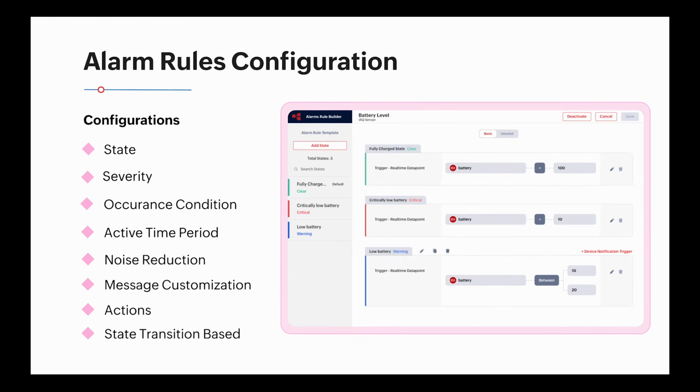Severity is a standardized label where we predefine names like critical, major, minor, warning, and clear, so that you can map those states to these predefined standard severities and have a prioritization, such as go and fix all the critical alarms first.